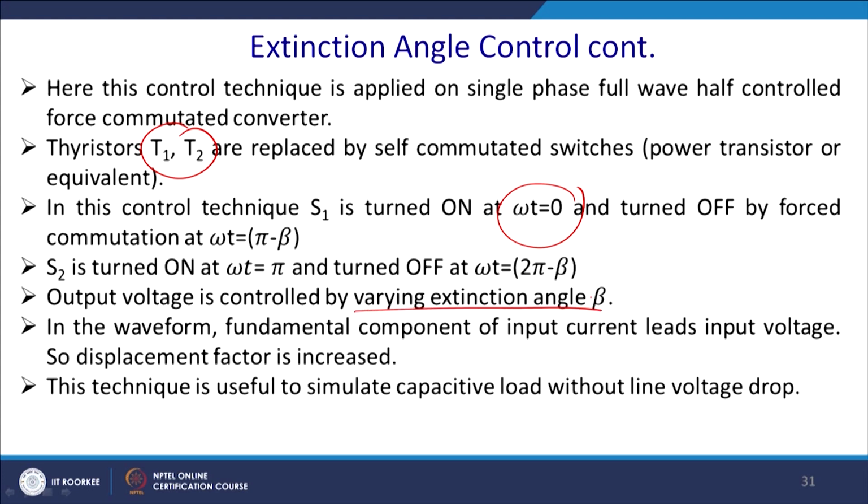So, the integration will change, and the fundamental component of the input current leads the input voltage. Thus the displacement power factor is improved, and this technique is useful to simulate capacitive loading without line voltage drop. So, this is quite a good application for it.